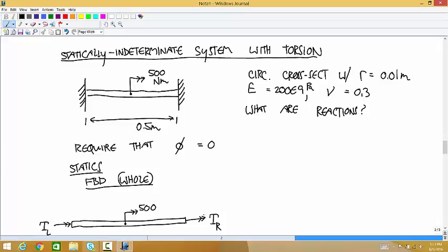But you can't calculate the stresses without calculating the external loads, right? Those stresses come from knowing what the internal loads are. You can't calculate the internal loads till you get the external loads. So you'd have to go through this statically indeterminate system process to figure out the external loads, then the internal loads, and then calculate the stresses. So this is all necessary stuff to figure out the stresses, which is usually our main goal.